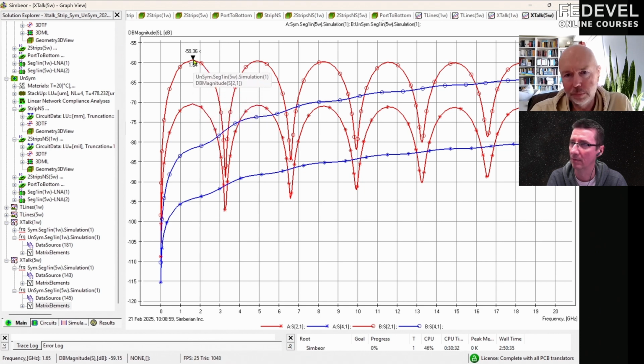It's still low. It's still low with circles. But it's 10 dB up in near-end crosstalk, as well as considerably up with far-end crosstalk, -84, -70, 15 dB up in far-end crosstalk.